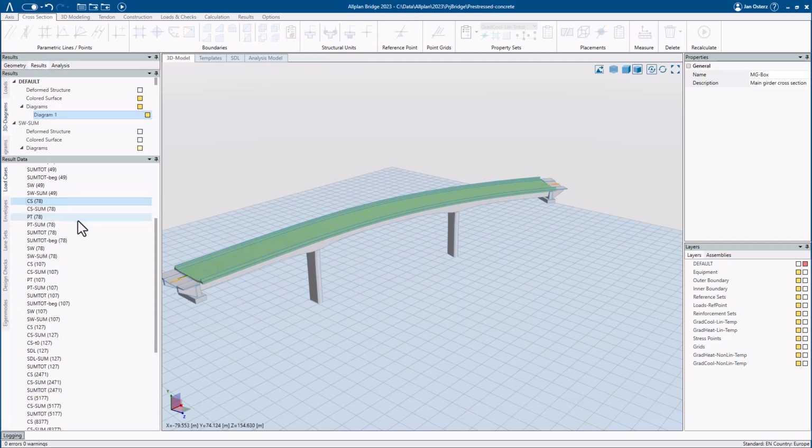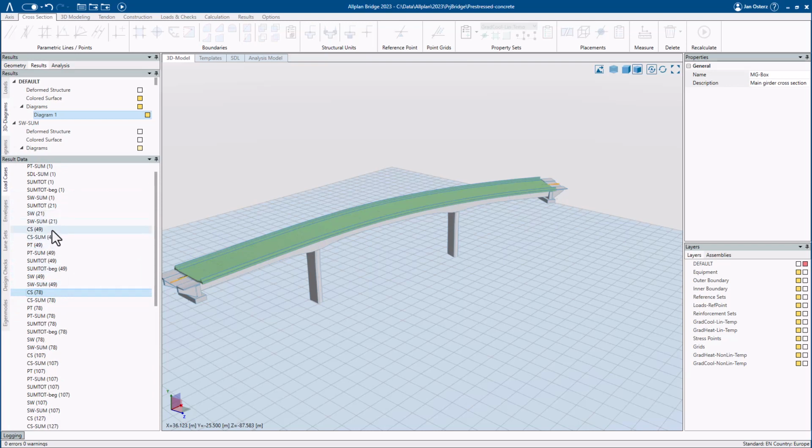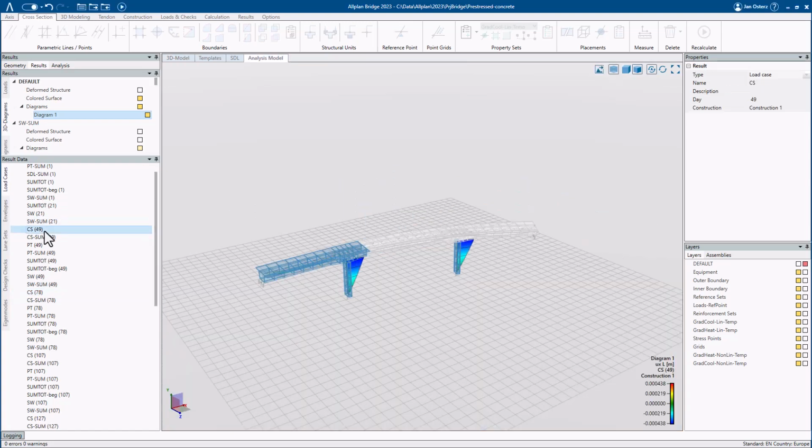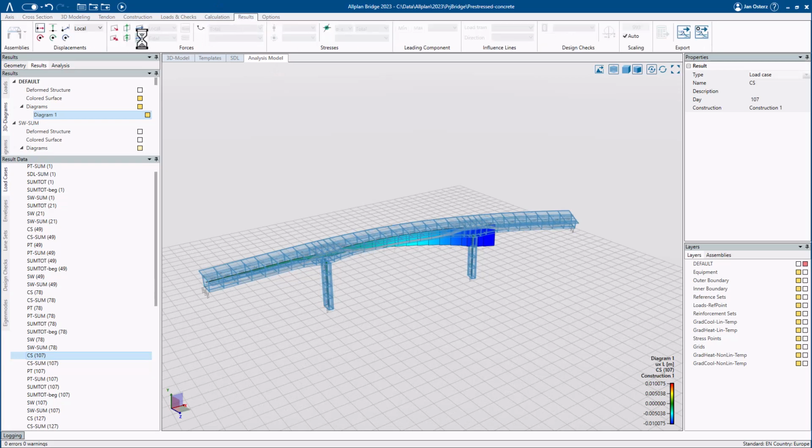So we see that we have now many different load cases, and as I was already mentioning, showing in the diagram, we activate or create additional tasks, additional creep steps that are being introduced here, where there was a relevant event, like activating, for example, part of the structure, or if we continue to the next stage where the second stage was activated, or then, of course, when the last stage was activated, we can have different result representations for our bridge.